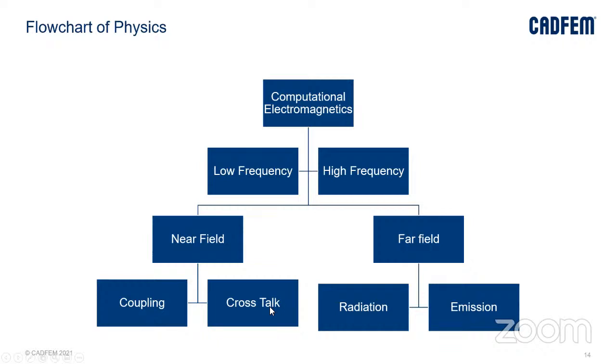When we are using it for some other application, say just a transmission line, and you don't want any coupling, then near field can actually cause crosstalk, where if two lines are very close by, the fields in one line can interfere with the fields in another line. In that case it would be crosstalk, which is not recommended, and we need to avoid it.